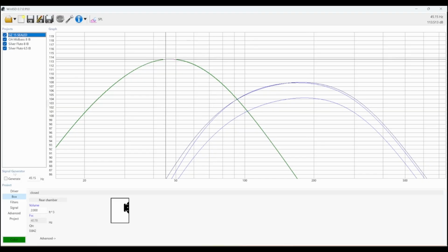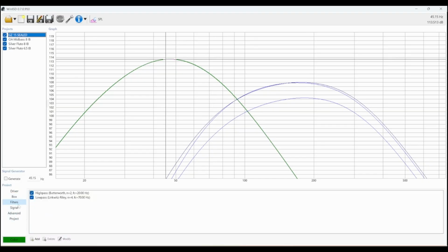You could simulate it with a filter, but in my opinion, it's best just to consider that something that all of these have, and you can tune around it anyway in your DSP. It's only a gain, not a performance drop, so you can tune it out, and if anything, it just saves you a little bit of power on the low end, which is great.